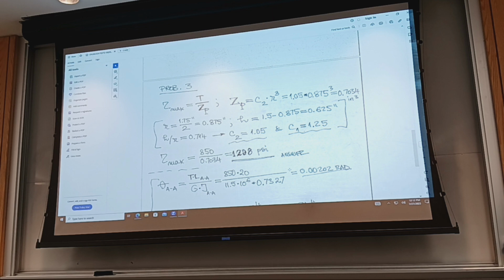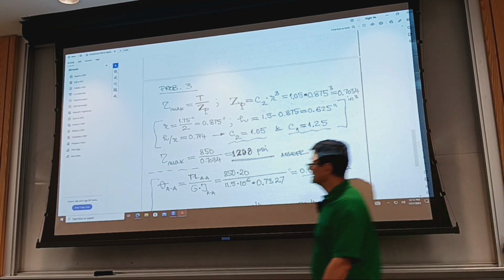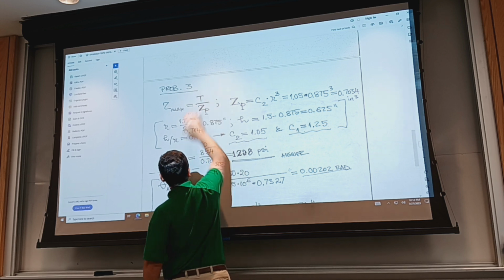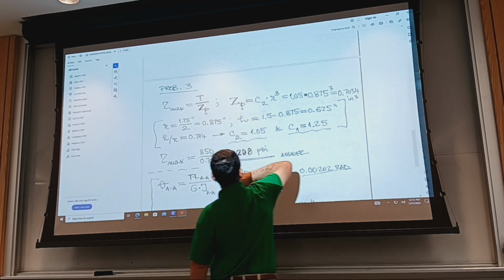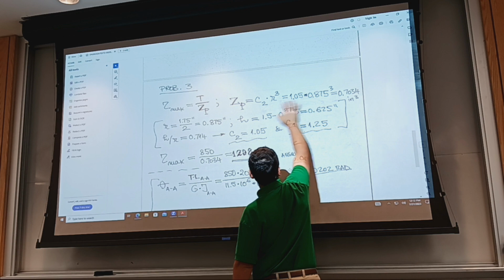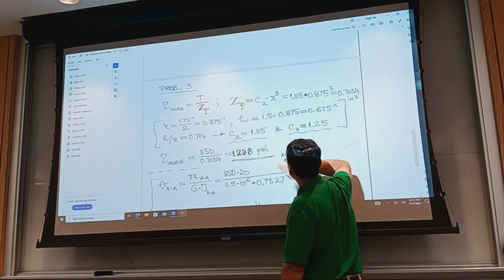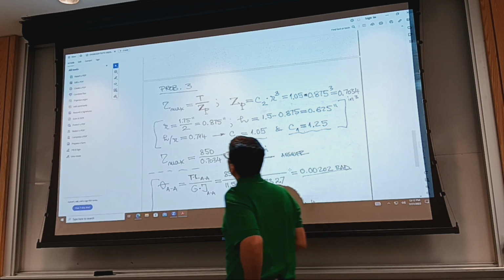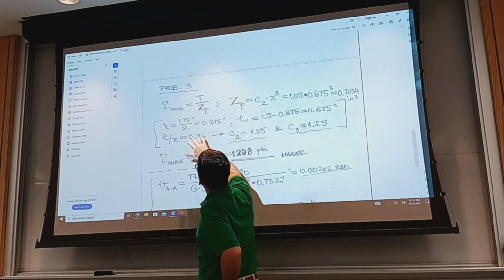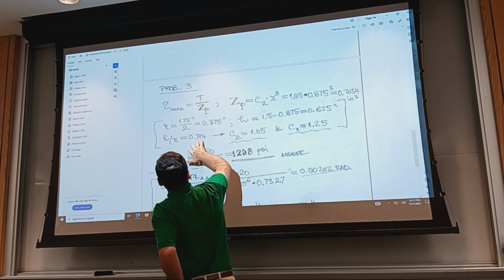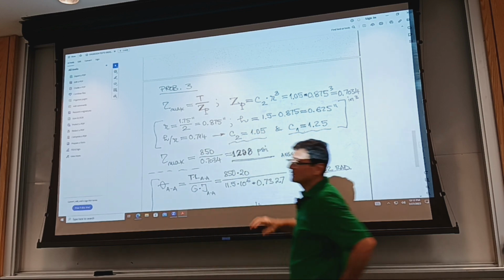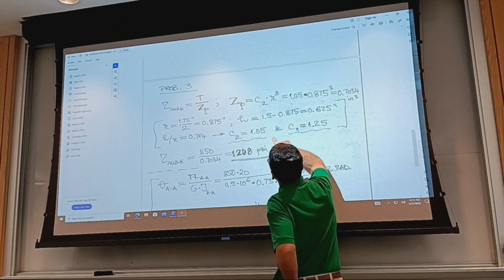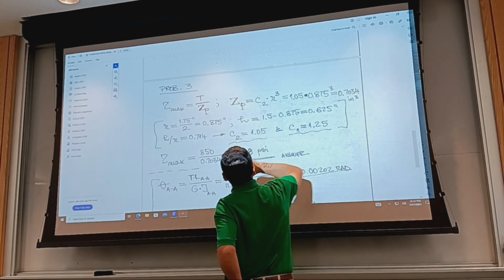The maximum shear stress due to twisting on the flattened section has the same formula, but the polar section modulus is now calculated using one of the coefficients, C2, and the radius of the original round shaft. So here I have evaluated the radius. Do these numbers look correct? Have you checked against your solution? And I extract also C2.